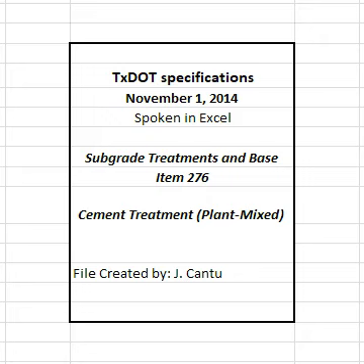5. Measurement. Cement treated base will be measured by the ton, cubic yard, or square yard as a composite mixture of cement, flexible base, and recycled materials. Measurement by the cubic yard in final position and square yard is a plan's quantity measurement. The quantity to be paid for is the quantity shown in the proposal unless modified by Article 9.2, Plan's Quantity Measurement. Additional measurements or calculations will be made if adjustments of quantities are required.